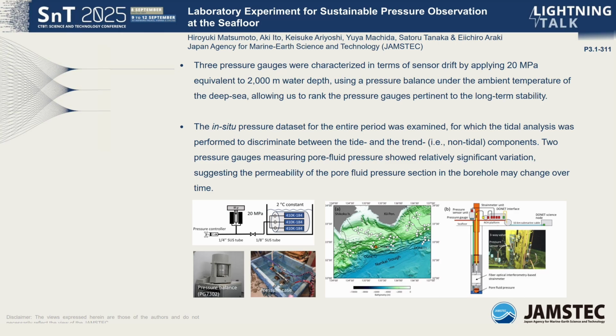So, prior to the installation, we pressurized all the pressure gauges to characterize each sensor. And after installation, we evaluate the in situ sensor drift. And in the presentation, we compare the results between lab tests and in situ observations. If you are interested in my topic, please come to my poster. Thank you very much.